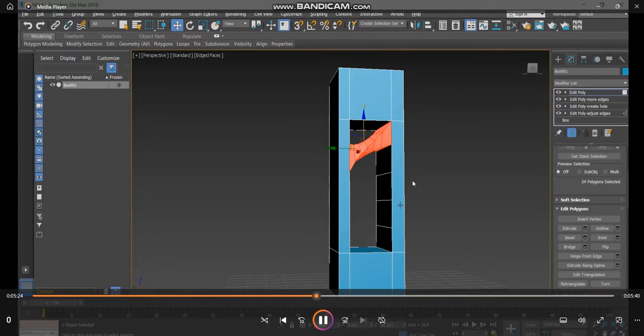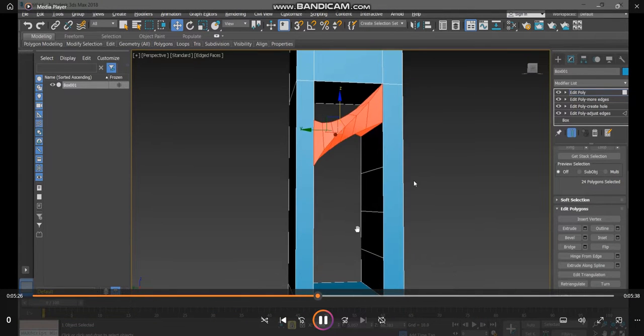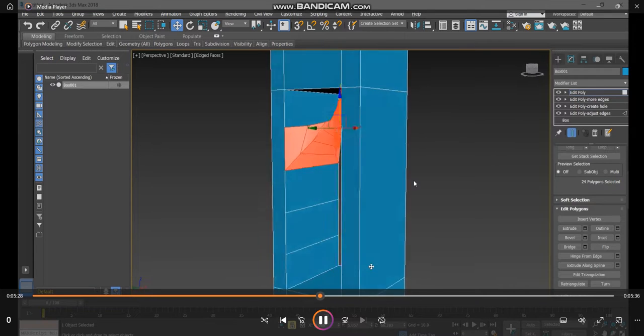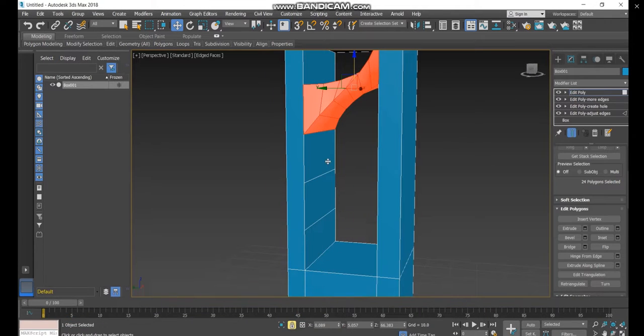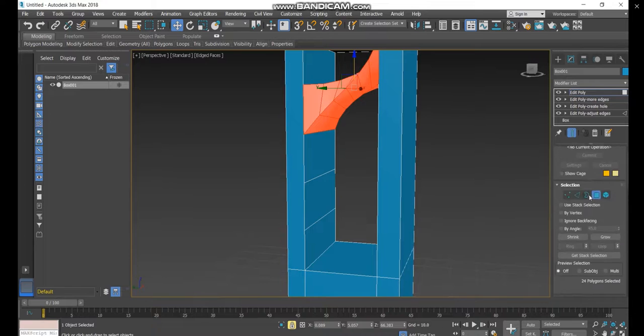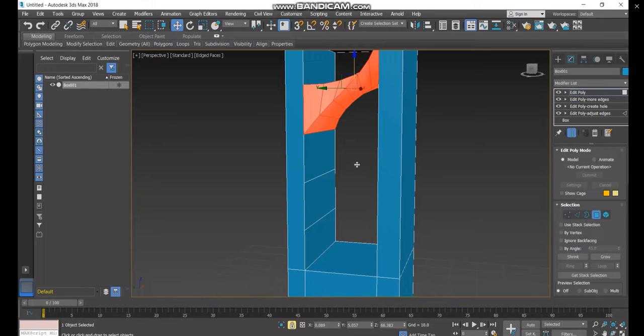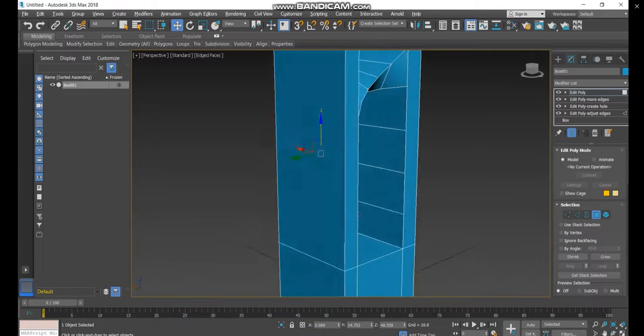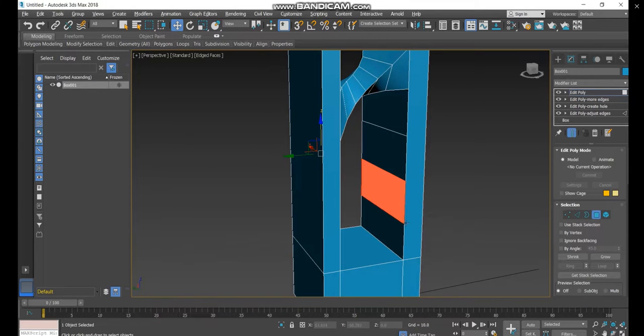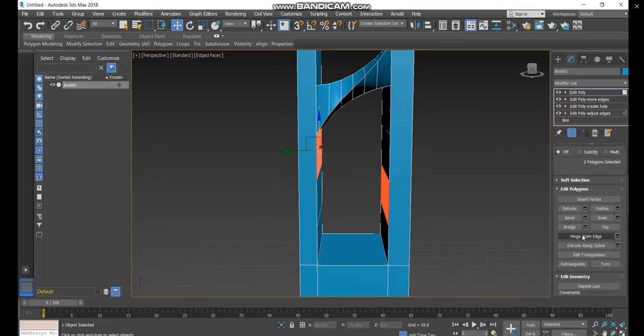Then, using the same settings, use two other alternate polygons in the same object. Keeping the polygon selection on, choose the two different alternate polygons and use bridge, which will take the previous settings, and connect.